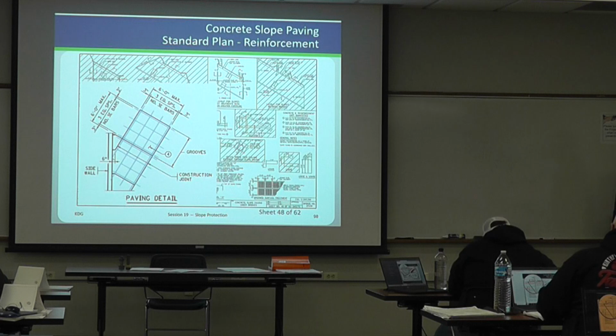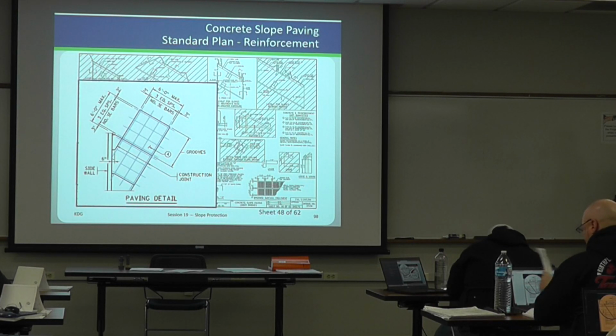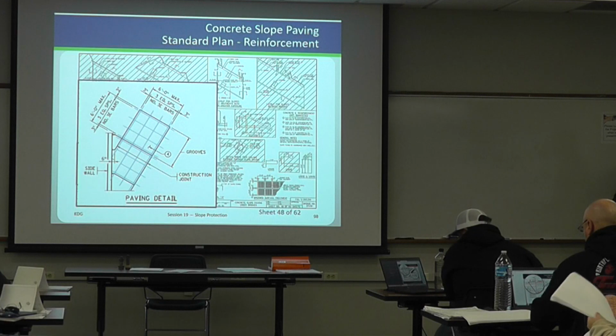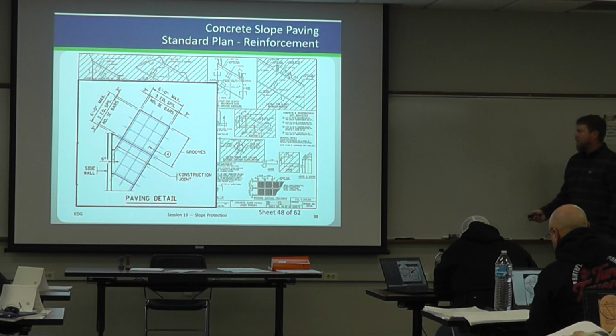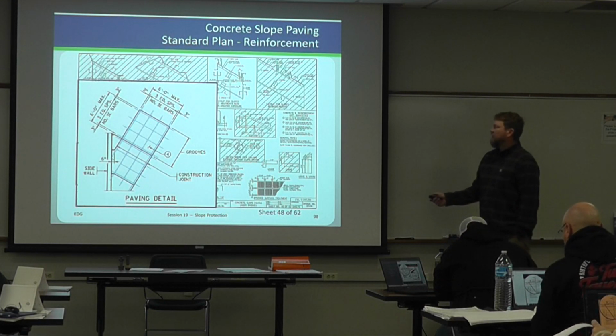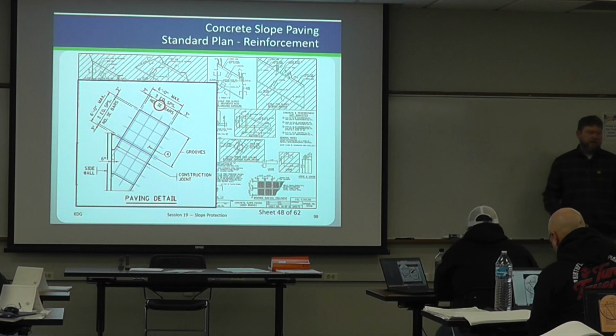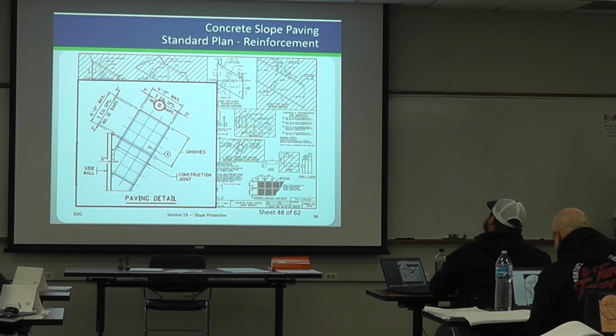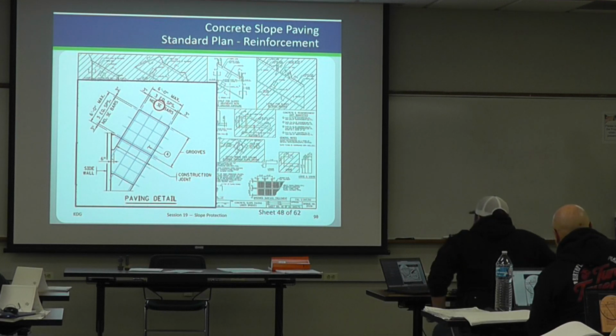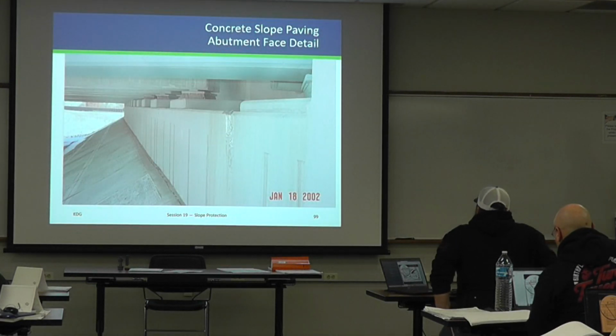So here is sheet 48 of 62 if you're interested. So we've gone to the colored rebar, which is blue. Is it not on yours? No. Maybe it didn't get printed that way, but yeah, a lot of times you're gonna see this. But anyway, the main point is, we're looking for number 3 bar, and the E is for epoxy coating. Like I said, in that picture I showed previously, that was an uncoated bar. It's an older picture. But you can find that information.